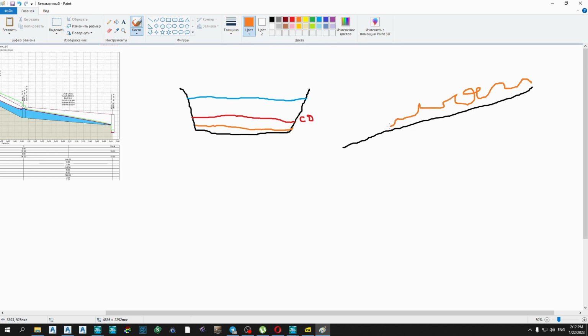Let's draw a profile plot. This first one is supercritical flow. Look at the water surface. It's very turbulent. It's very sharp maybe. And this blue one is subcritical flow. Very slow, non-turbulent regime, like a common regime of rivers.